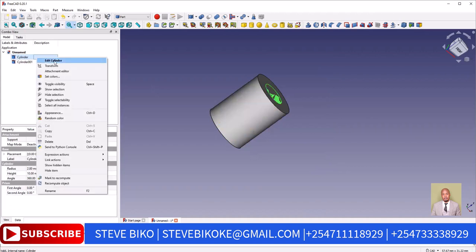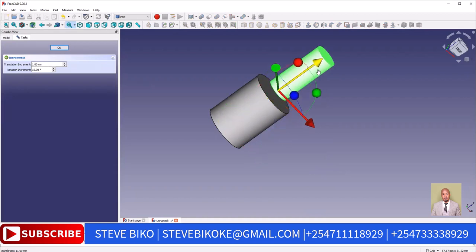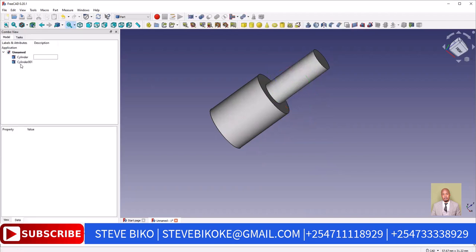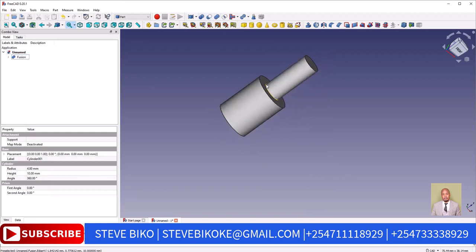Then we transform it to be on top of the other. Then we press OK. From there, we click all the cylinders, then we union them. This is to join them and ensure that it is one solid axle.